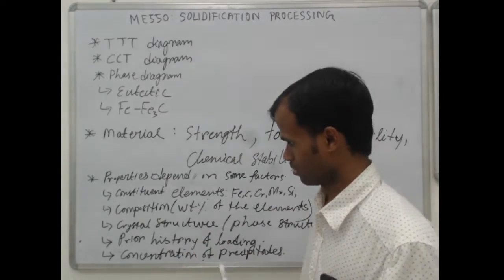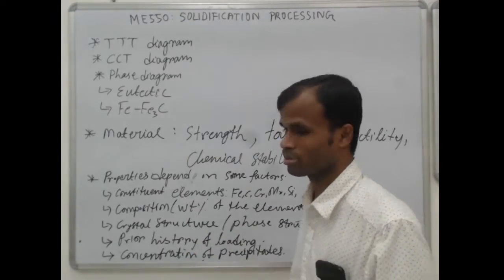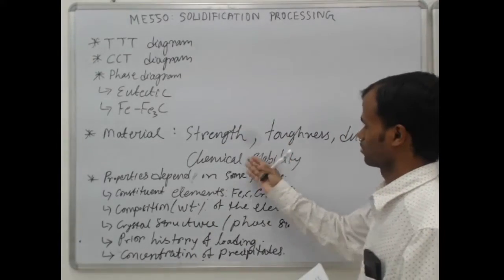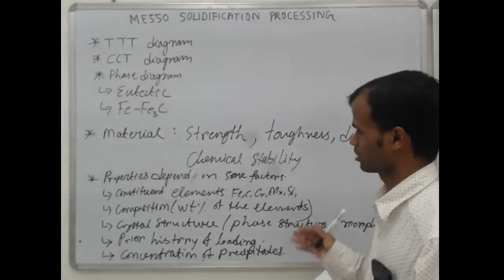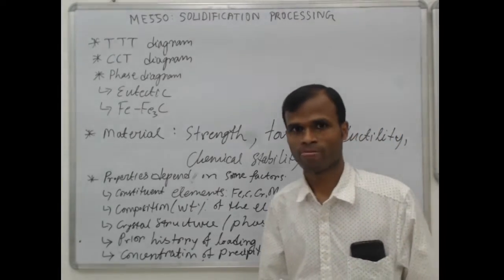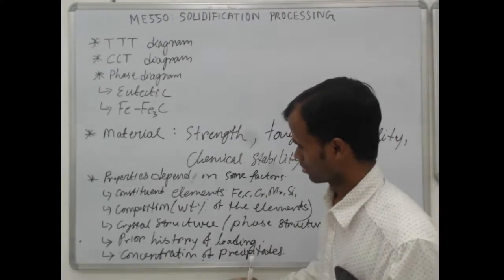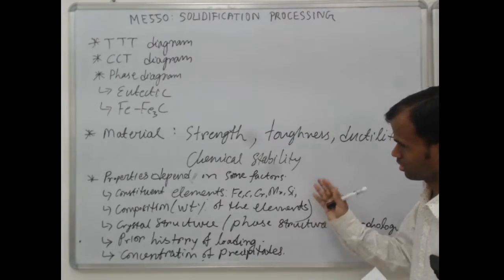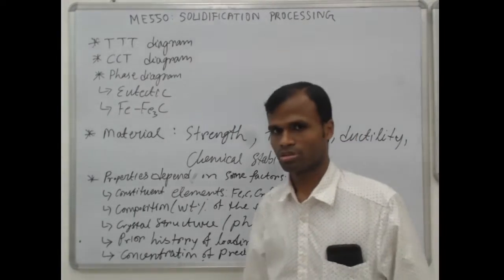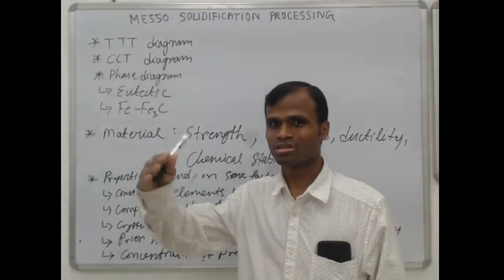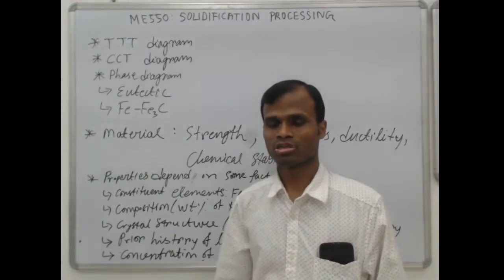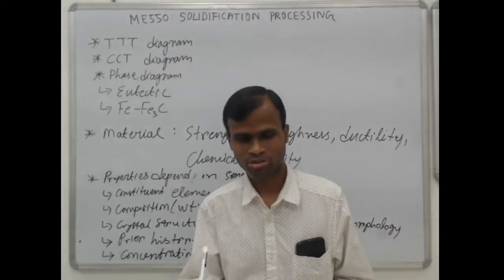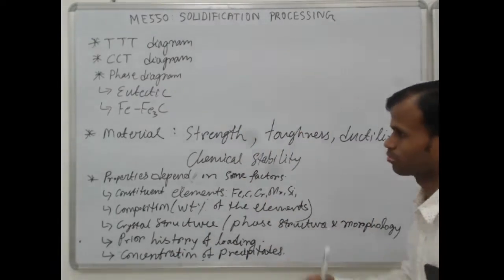You can also have some precipitates which are very bad for mechanical properties or some chemical properties, such as oxidation or corrosion. Sometimes chromium carbide precipitates in some stainless steel at a certain range of temperature are very harmful for intergranular corrosion. So precipitation also influences the properties.